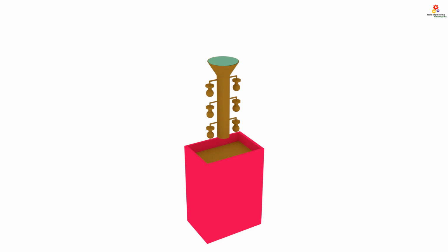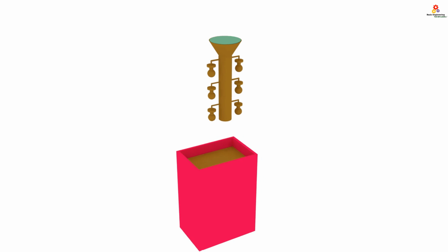This slurry mixture is water based and it contains silica and binders. We should dip this tree multiple times so that we have the required thickness of ceramic coating on the wax patterns. Let the tree dry. After drying, it will be hardened to some extent.